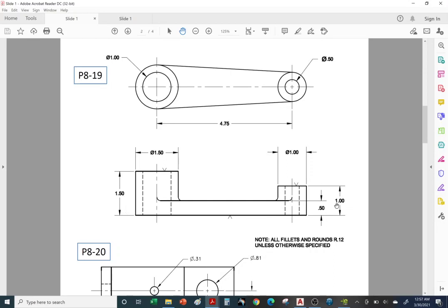We tend to want to group them together, but it just doesn't make sense to have the 150 over here on the right, because then we would need a long extension line. So we're going to take the oldest one, the 150, and just set it over here because it just makes more sense to dimension to this edge or this vertex versus putting it here and extending our extension line all the way up to this point. So it's better to keep this one on the left and these two on the right. Cool thing is you have the middle sibling taking care of the little sibling.